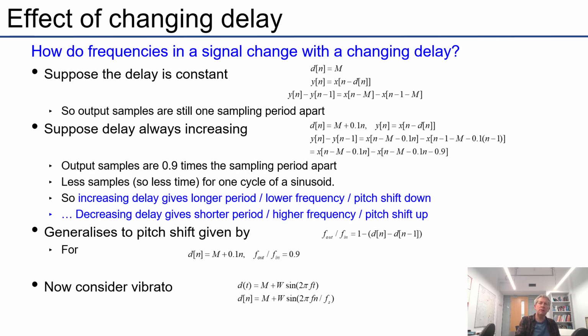So increasing the delay gives a longer period, right? That's intuitive. Well, a longer period gives a lower frequency, which means that the pitch shifts down. On the other hand, decreasing the delay gives a shorter period, which results in a higher frequency, or a pitch shift up.